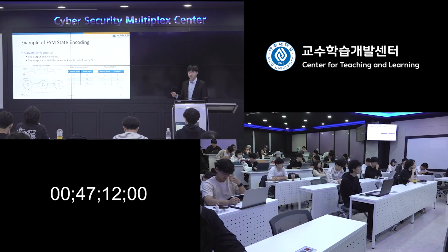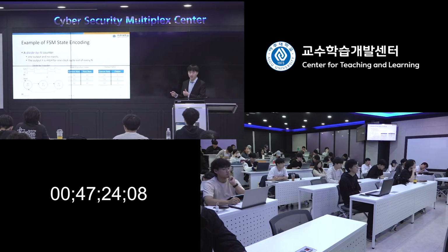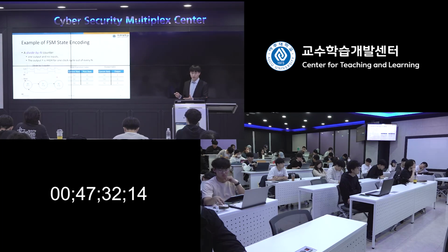you see, from the timing diagram, you can directly see the difference, right? Every 3 cycles, the output is true. 1 cycle, second, third, and the 3rd cycle. Every 3 cycles, the output is 1. So it's called, in this case, a divide by 3 counter. Then it's a very simple logic, right? If you have a clock, then you can easily generate some divided clock.